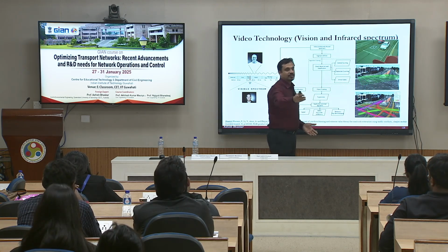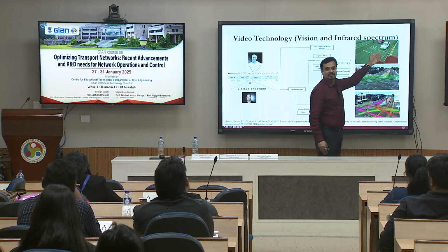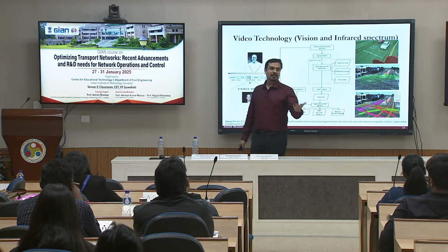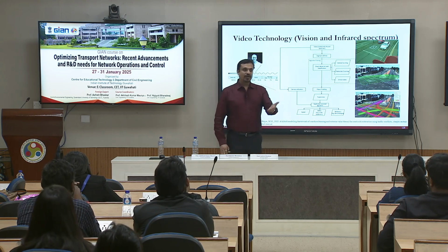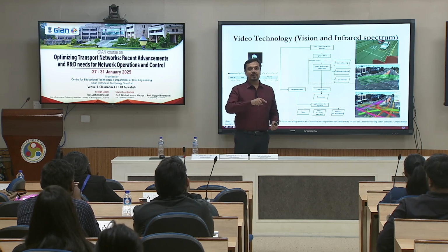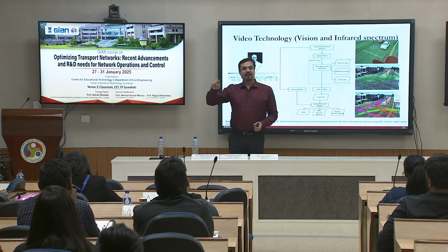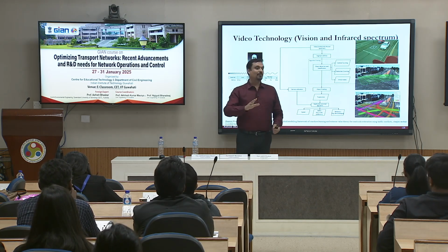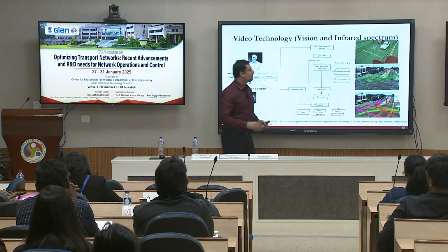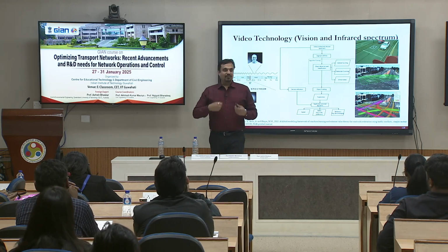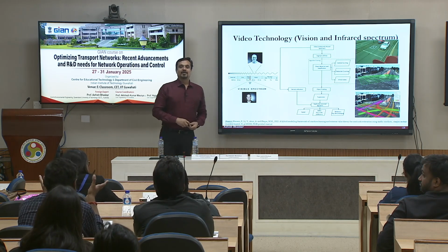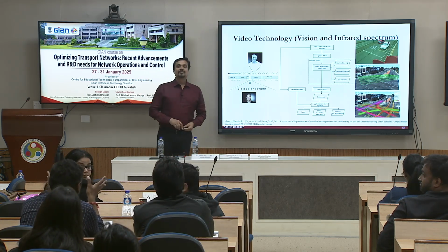And generally, if they are using it as a counter, they will be using something like this, more or less. So they are basically emulating the loops. You got loop counts, you got loop occupancy. If you are lucky enough, they might have given you individual arrival and departure, very lucky, or maybe they might have aggregated and given you an aggregated value. But let's say you are lucky enough, they give you the pulse. It will be useful for gap acceptance studies. Actually, that is what we do mostly, for the gap acceptance studies.